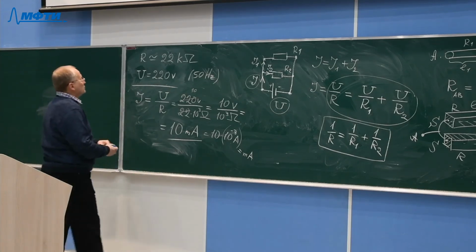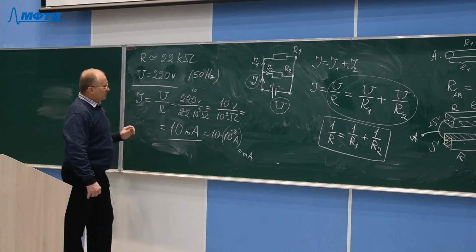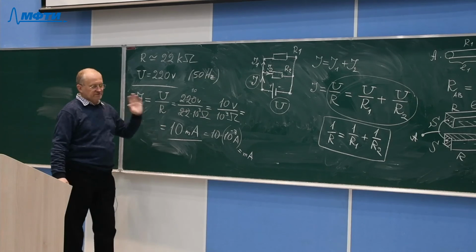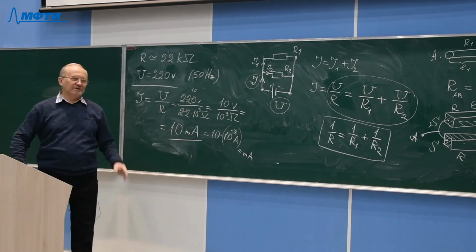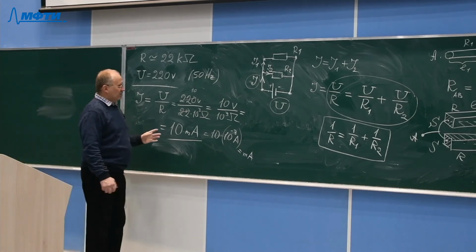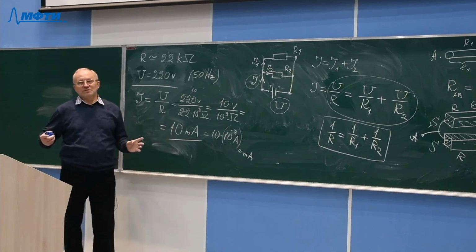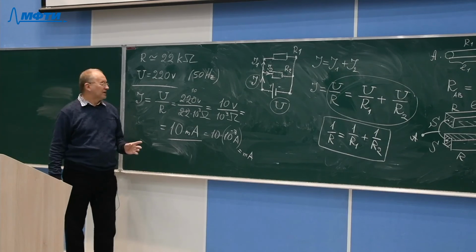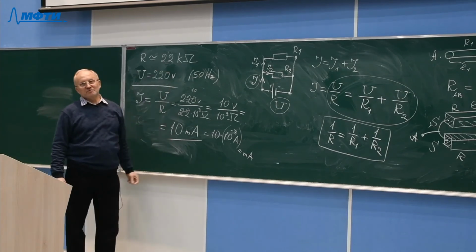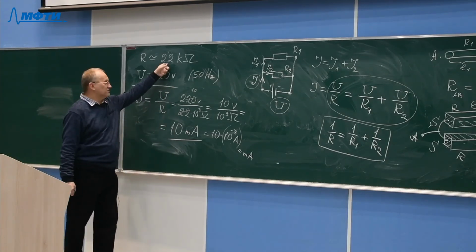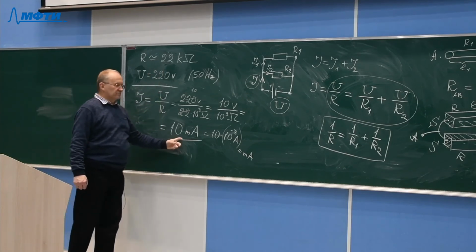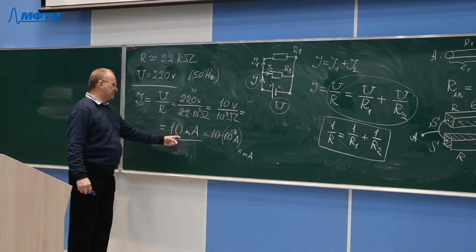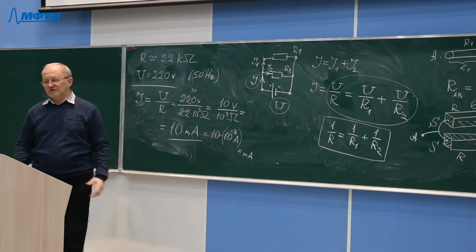So it's a varying factor, and sometimes a person touches 220 volts and says, oh, nothing, I can easily tolerate it, nothing at all happened to me. But next time the situation may be different, the humidity in the atmosphere may be different, and the resistance will be different. It may be half that value, and the current which flows through the body will be twice or more than that value, and that may be very, very dangerous.